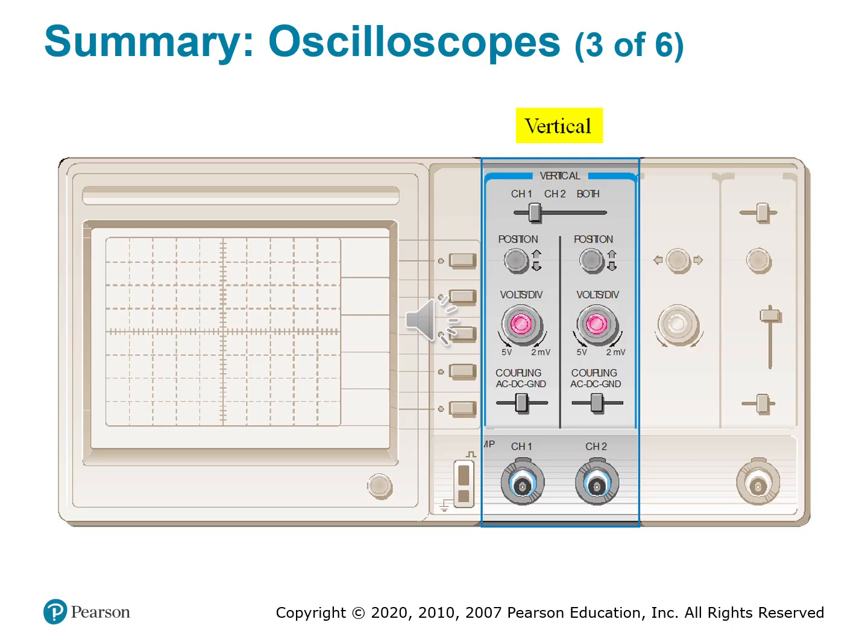The volts per division knob, this sets the vertical scale. So for example, if set to 5 volts per division, each grid division on the screen equals 5 volts. Turn it to 2 millivolts per division, and you're now analyzing millivolt level signals. Adjusting this is like zooming in or out on voltage.